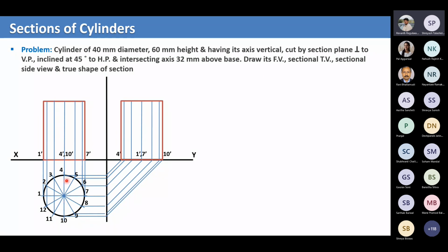So now this circle you should divide accordingly. You can divide it into 4 parts also, just 1, 2, 3, and 4, that means each sector having 90 degrees. But then you will get a very bad answer. So minimum you should divide it into 8 parts. That means each sector should be 45 degrees, minimum. Only then will you be able to get the perfect result.